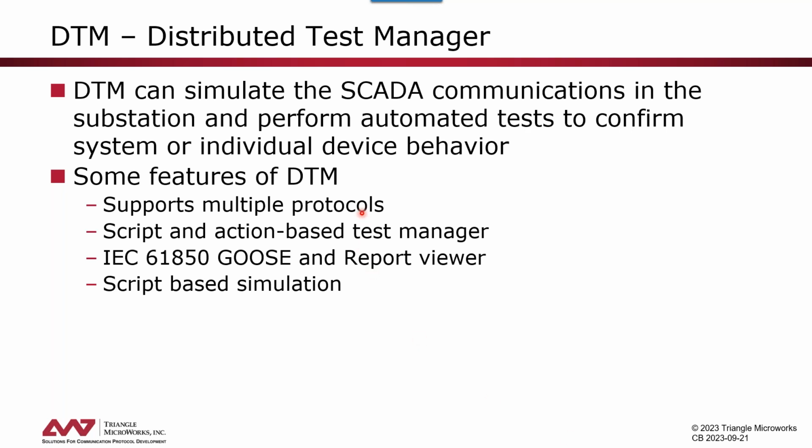It supports multiple protocols. It includes a script and action-based test manager. It has a 61850 GOOSE and report viewer, and the focus for our discussion today, it supports a script-based simulation of a system that is described in SCL, the System Configuration Language.